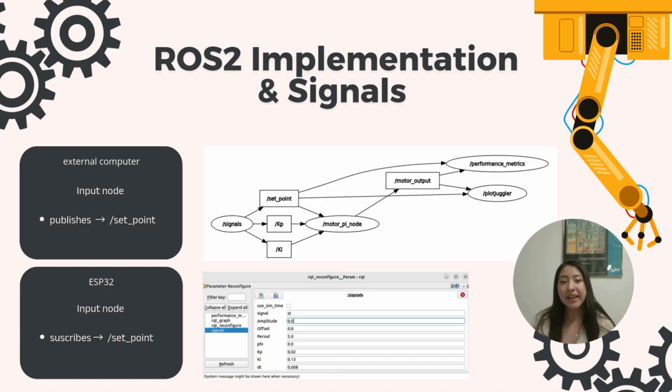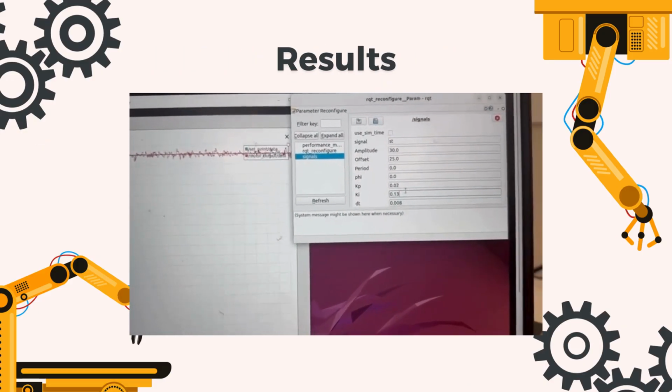Also, a low-pass EMA filter was applied to the encoder speed signal to reduce measurement noise. Due to the noise of the encoder, derivative action wasn't necessary as it would only amplify the filtered signal's residual noise. This is our motor with fine-tuning variables.